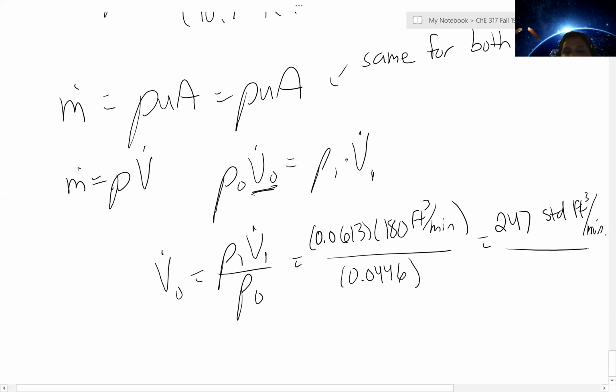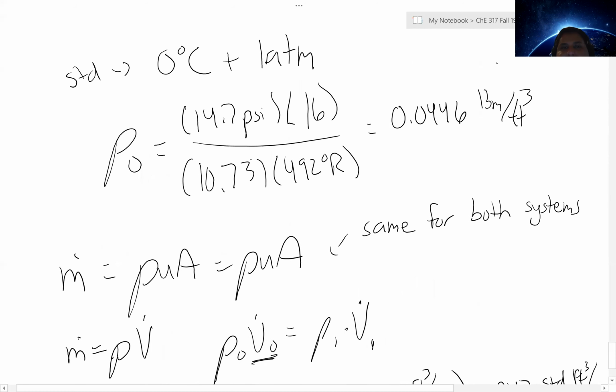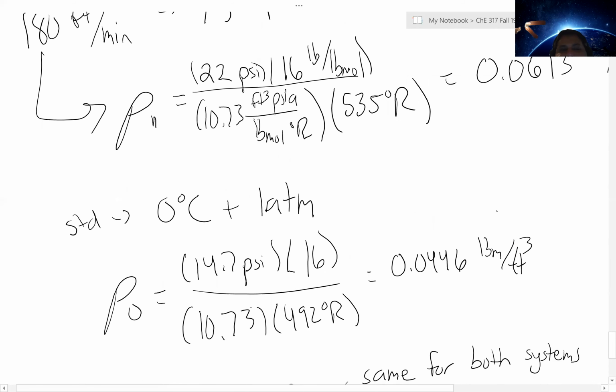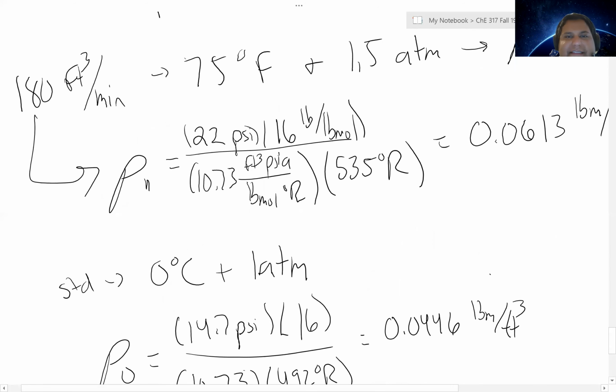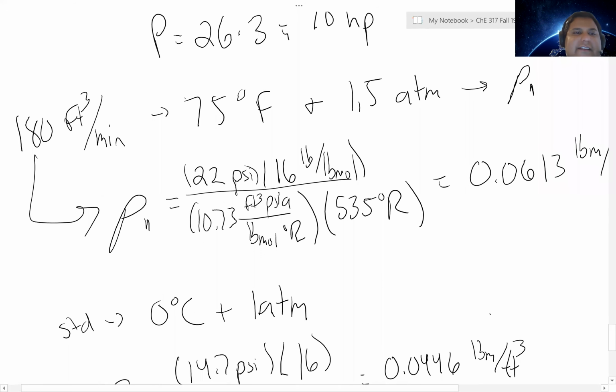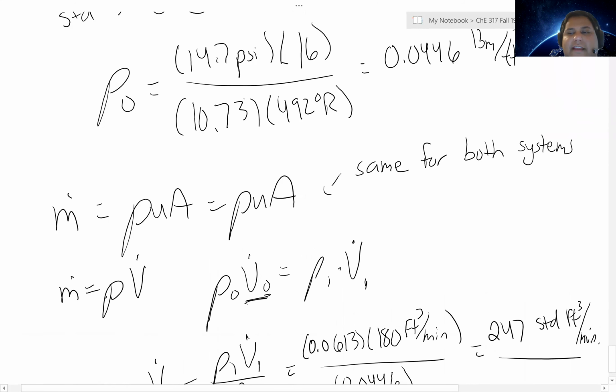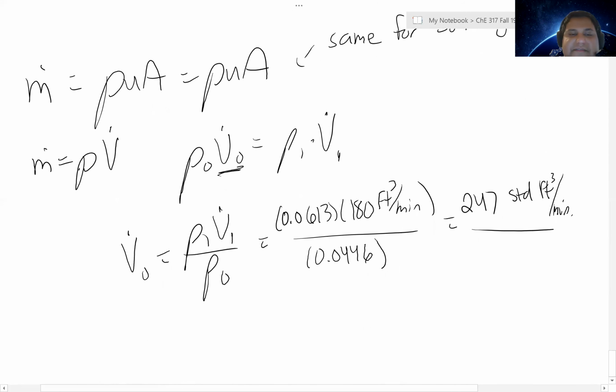And so by applying continuity, you can correct for any temperature and pressure that you're doing your flow rate reading at by essentially doing a comparison of the fluid densities. So a little bit of a tangent, but hopefully that makes sense. And so now you can see taking it from a measured flow rate to putting it into those terms of standard flow rate. Does that make sense?